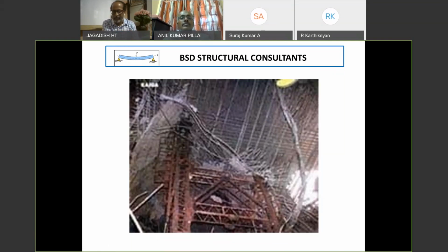I'll tell you what exactly happened there. This particular dome structure, the half portion of the dome, is now resting on the tower. You can see all the pre-stressing cables here exposed. These cables have become straight. In the photo, you're not able to make out. Cables in the other direction are still intact in concrete. The upper layer of cable didn't come out because they delaminated at half thickness. In the lower half, cables have come down. Upper half cables are there as they were.